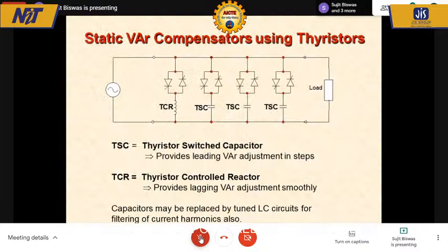In a distributed generation, why do we need such systems? That's a big question. Well, if we have a lot of distribution systems using cables particularly, and at night most of the loads are off, then you are going to get a rise of voltage at the load end because of the Ferranti effect through the cables. So you have to do some sort of inductive connection at this end, where you might need the TCR to be operated alone.